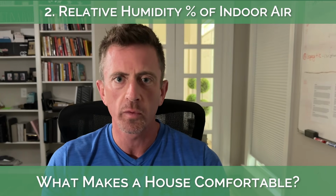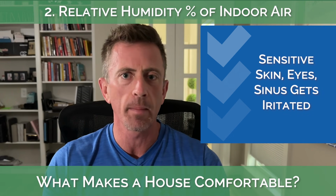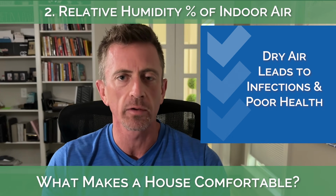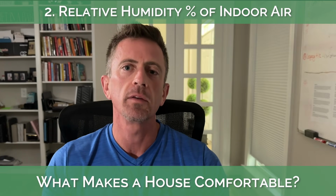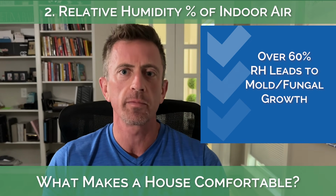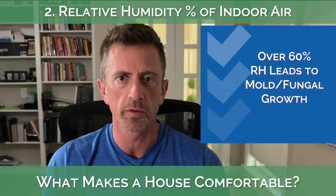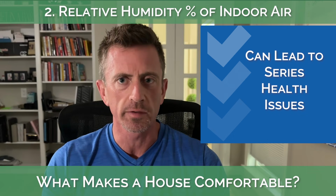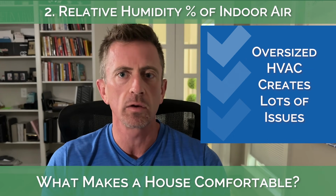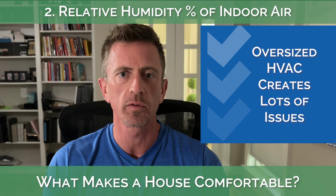If it goes below 40%, your eyes, skin, mouth, and sinuses will become dry and irritated, which can lead to infections and other health problems. If the relative humidity goes over 60%, it creates conditions ripe for mold, mildew, and fungal growth inside your home, which can lead to serious health issues as well. This is why oversized heating and cooling systems cause so many health and comfort problems.